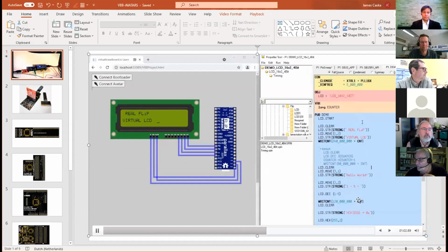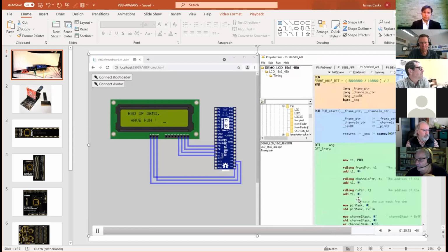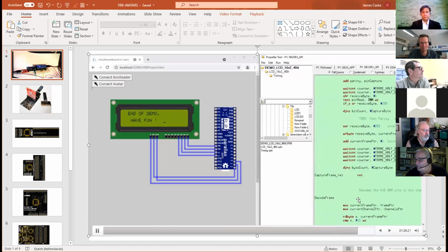So the idea here is I'm creating virtual hardware that you can connect to actual modules, and they work and look and feel like real hardware using the same code, and you're using these avatar interfaces as basically dynamic logic analyzers, if you like. So the essential one chip version is using these new PIC18F47Q84s, which have got some really great I/O capabilities with DMA and all sorts of nice things.